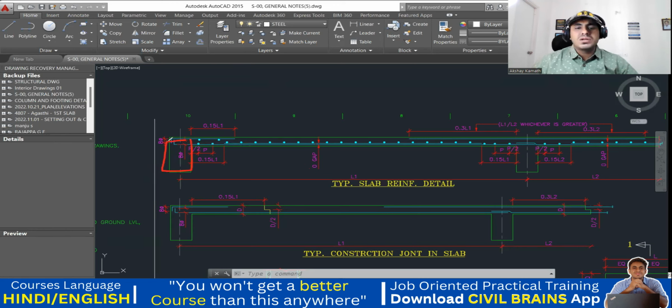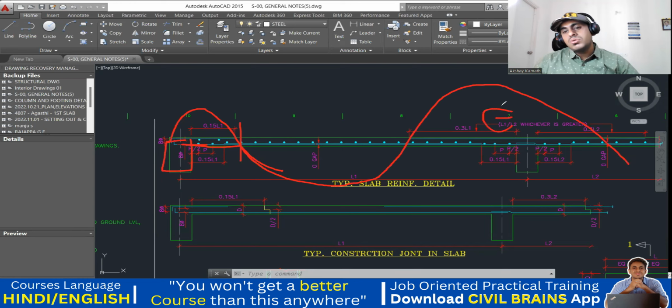It's a small bending moment we get. The intensity of the bending moment has been found to extend somewhere up to 0.15 only, since you have only this side. Whereas this is a continuous support, due to the slab on this side and the slab on this side, a huge negative bending moment is created. Since a huge negative bending moment is created, the impact of that bending moment is almost at 0.3 and 0.3 on the left and right side. Since the impact is on the higher side, up to this distance you are getting that negative bending moment effect.